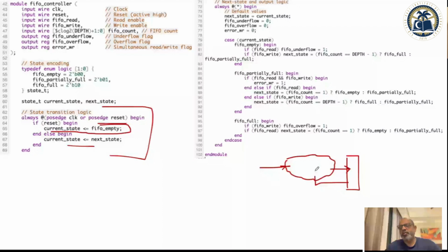So it is precisely doing this. So the cloud is the initialization. Remember, it is important. Otherwise, it may instantiate latches. So whatever variables you have in the combinational cloud, make it a practice to assign them a default value before you enter the intelligent part.